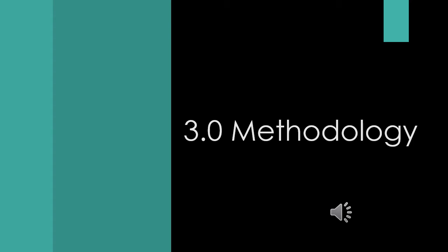So after modeling the product in the geometry, we can move on to 3.2, which is the meshing. In the meshing section, I will explain the steps of how the mesh was generated using ANSYS. The mesh was generated using the sweep method at first, where we did the overall meshing for the whole pipe, and then for the edges and inner parts of the pipe, we used size meshing.